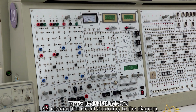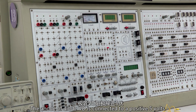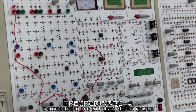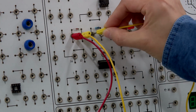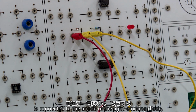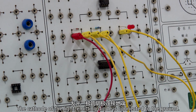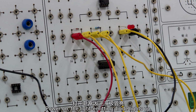Let's connect the circuit according to the diagram. The anode of diode VD is connected to a positive 5 volts. The cathode of the diode is connected to one end of a 470 ohm resistor. The other end of the resistor is connected to the anode of the light-emitting diode. The cathode of the light-emitting diode is connected to the ground. Power on. The light-emitting diode lights up.